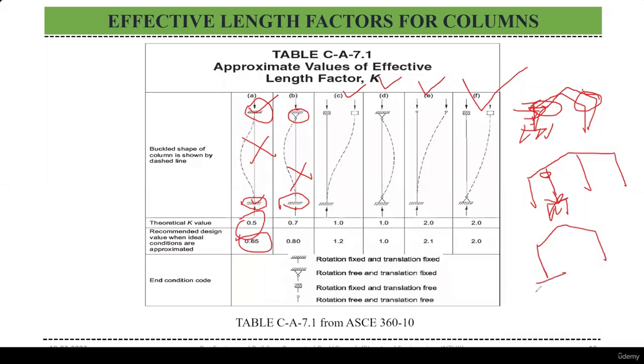For a rigid frame, we have a fixed base. Generally, for any frame, we have to check for pinned base only, first of all, because pinned base will give you a more economical footing, right? Also, we can taper the sections for columns, but in fixed base, there will be huge footing and we cannot use tapered